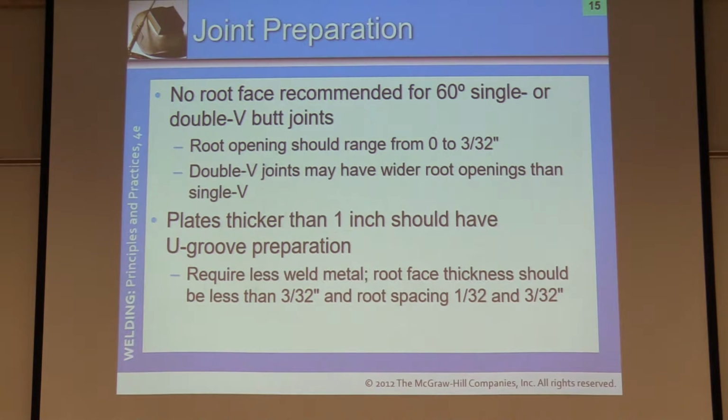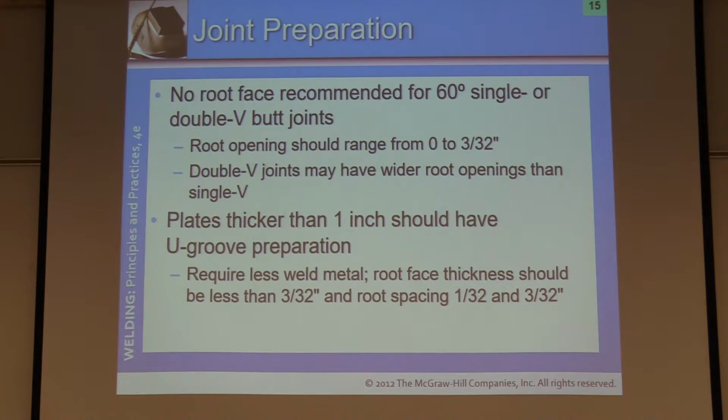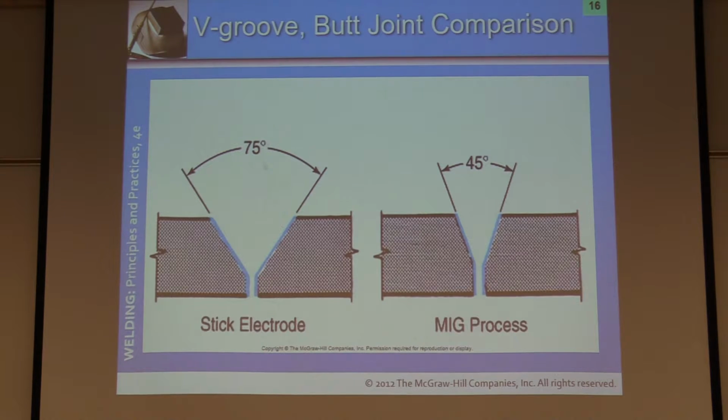Plates greater than 1 inch should have U-groove prep. They require less weld metal. Root face thickness should be at least... Most of the time we're not going to see a lot of 1 inch on gas metal arc welding. We'll be seeing a lot more of that with flux core. So therefore, fusion's not really the issue with flux core that it is with gas metal arc welding.